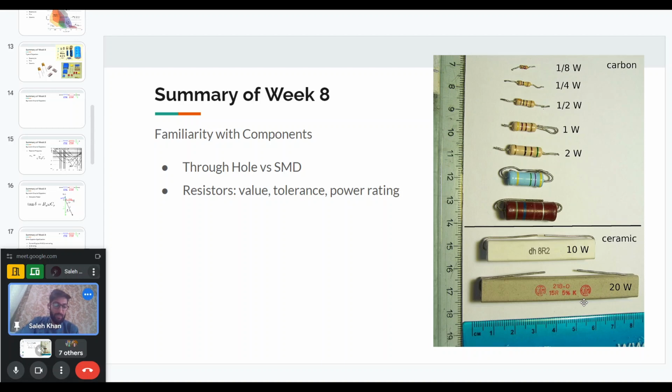So in general, if you have a resistor on the power side, the power electronic component section, for example in your snubber section, or for voltage sensing, then you have to consider how much losses it has to dissipate, and choose your resistance power rating based on the losses that you are expecting.